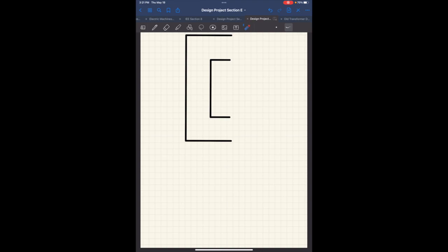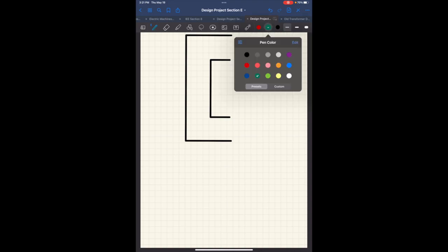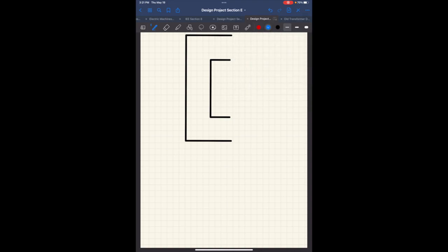Let's start with the low side cable. The reason I want to start with the low side cable is because it's the bigger of the two. I'm going to draw the low side cable, by the way, in blue. So basically, we're going to wrap the turns like this. You can imagine this is going like this, right? And then we're going to wrap the next layer.